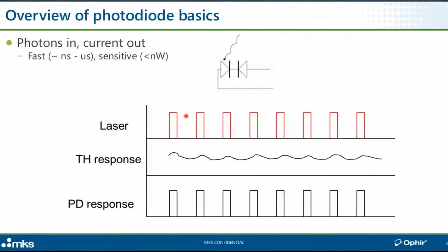So here we have a pulsed laser. For higher powers, typically tens or hundreds of milliwatts and upwards to 100 kilowatts plus, we usually use a sensor based on a thermal detector, usually a thermopile, to measure the power for all kinds of different reasons. Those kinds of sensors have a physical response time on the order of a second or seconds.